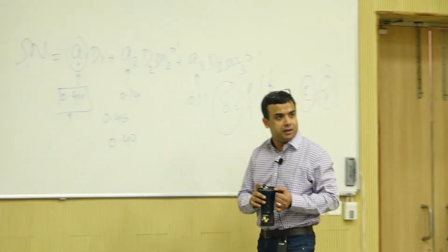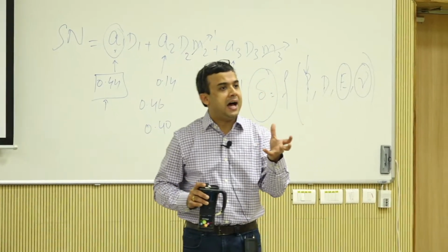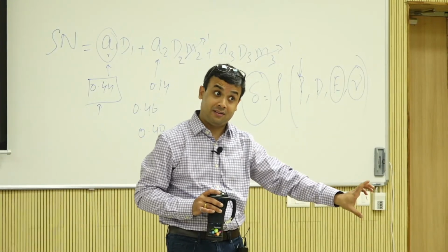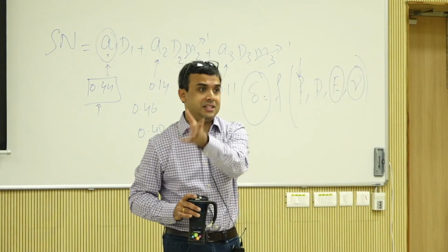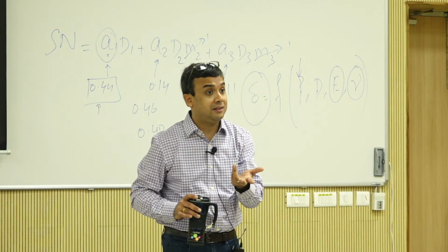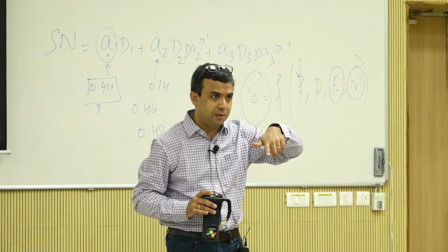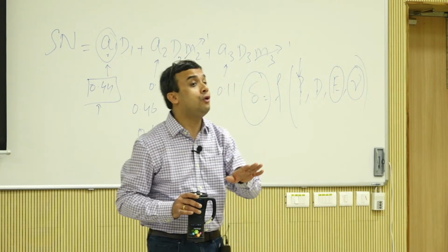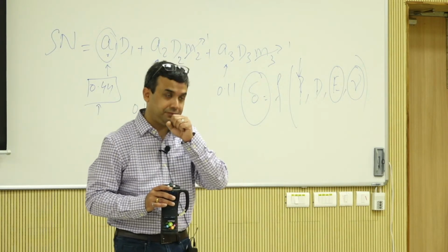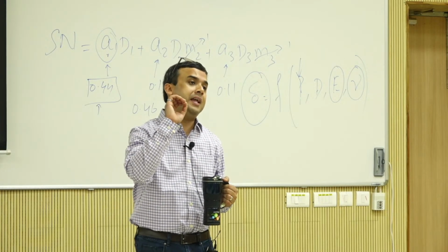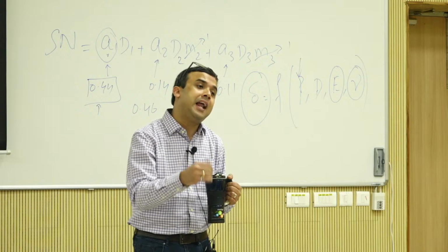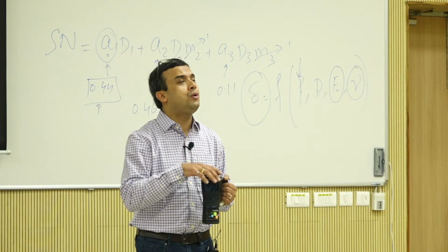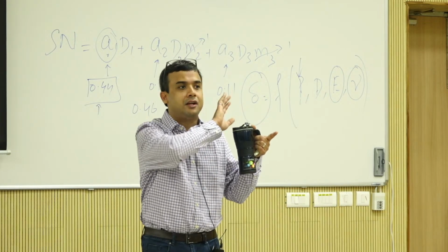That's the forward. Now let us say in a beam, I know load, I know deflection, I know I, which is a geometric property. I don't know E. Can you calculate E? You just rearrange the terms, right? That is back calculation. No. ME design is a forward thing. Back calculation is when a pavement exists and you are trying to determine its properties, right? Again, I don't want to confuse you, but back calculation has nothing to do with ME design.